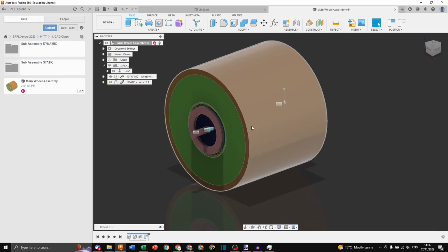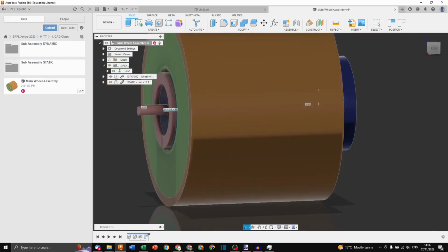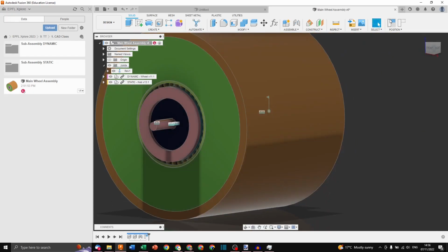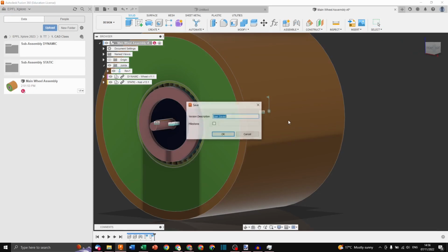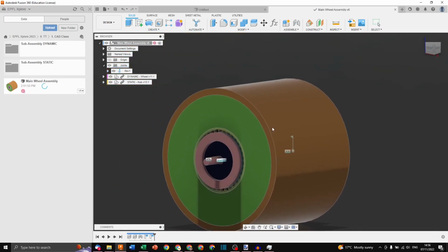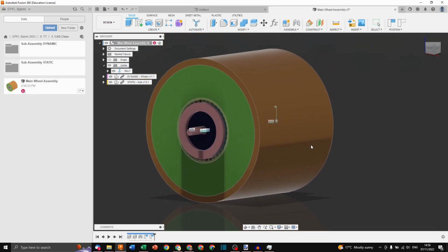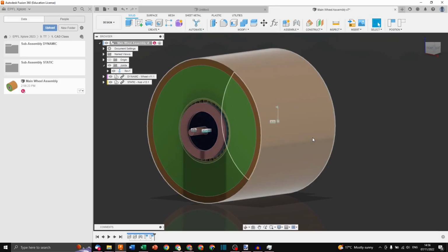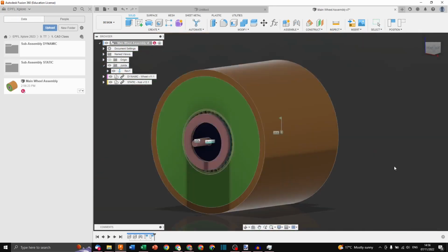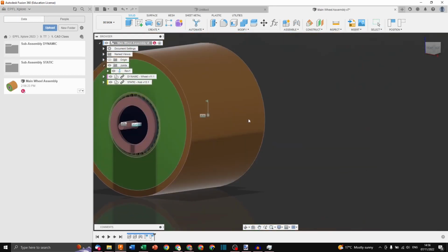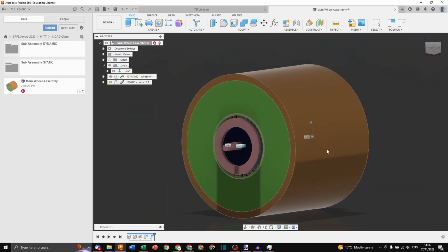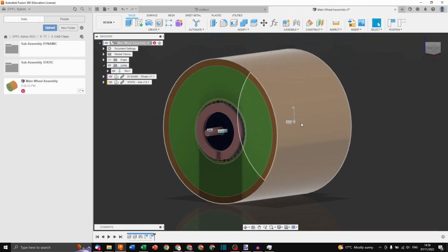I should be able to show you that the wheel spins by simply rotating the wheel by pulling on it with my mouse. I'll first capture and save, and you can see that in theory, if I do this, well, that's weird. The whole body's moving. That's because we forgot the most important joint of them all, the ground. If we don't tell Fusion which part cannot move, it's totally allowed to let us move in space like this. Because, well, that's the main DOF. Like, there's still left, right, up, down, and rotation that we didn't say that the whole model couldn't do.